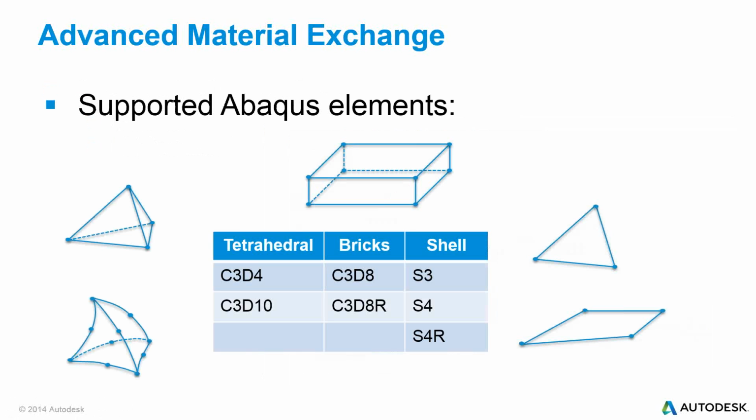Here's a list of the supported Atticus elements. Currently we support C3D4 and C3D10 tetrahedral elements, that would be for solid to solid mappings, as well as C3D8, which is an 8-node hexahedral, and a reduced integration hexahedral for solid-to-solid mapping.